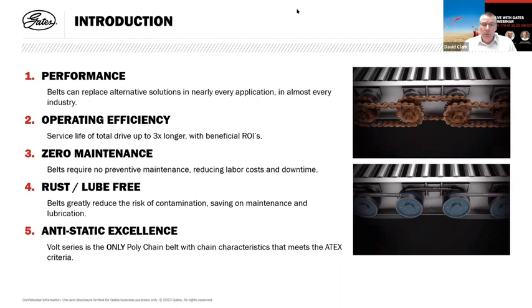Many of our belts, for example, the Polychain Volt, our highest rated standard synchronous belt, is ATEX approved on those drives on which belts can be fitted, and it meets the requirements of ISO 9563, the standard for static conductivity. So belts are a well-rounded solution, and in this case we're talking mainly synchronous belts to give you increased efficiency, lower maintenance, and longer lifetime.